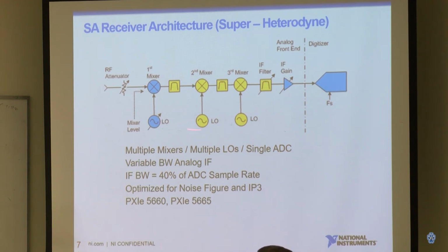So you're using multiple local oscillators. Remember I mentioned using a super heterodyne or IF down converter, you have a dynamic range challenge because your filter will degrade your dynamic range, and as you go through multiple mixers, your dynamic range or linearity will be degraded. So you have to be really balanced about your dynamic range and your linearity using multiple stage conversion. And most of the components are really expensive, so this is why it costs more money.